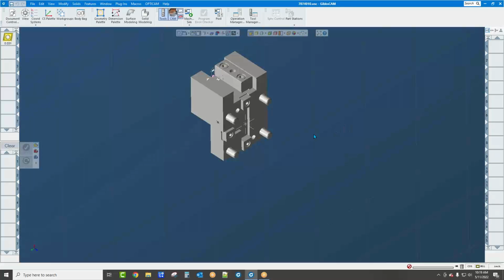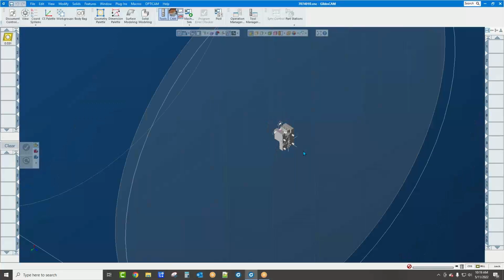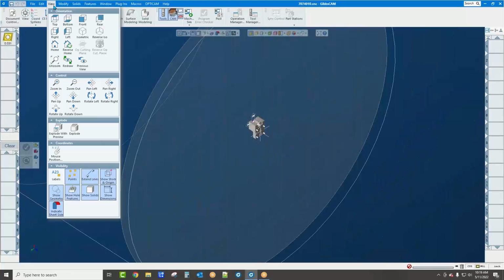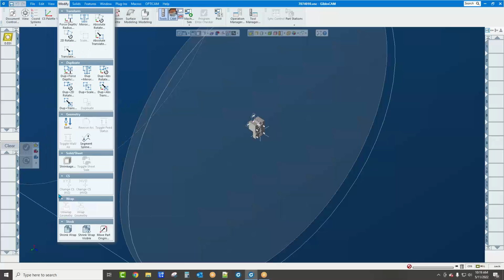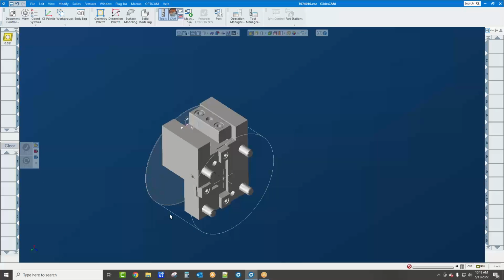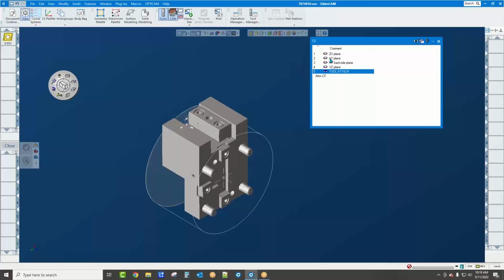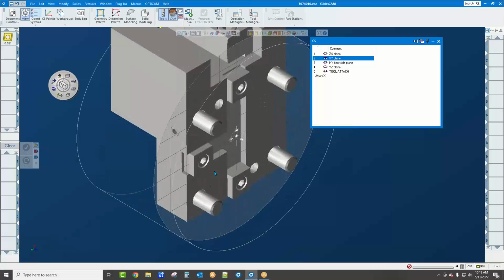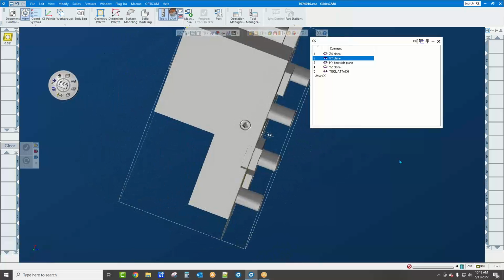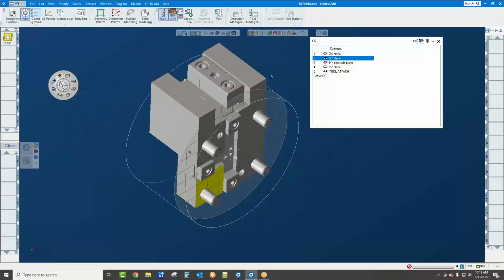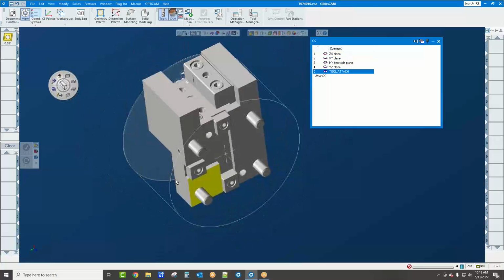once again, it is all about coordinate system. Now, I typically use C-axis horizontal lathe. Let me shrink wrap this. I use C-axis horizontal lathe. And for a lathe tool holder, we want to be in our XY plane here, where this would be where it would mount to the turret. So you can see that's 0. And then I need a tool attachment point.